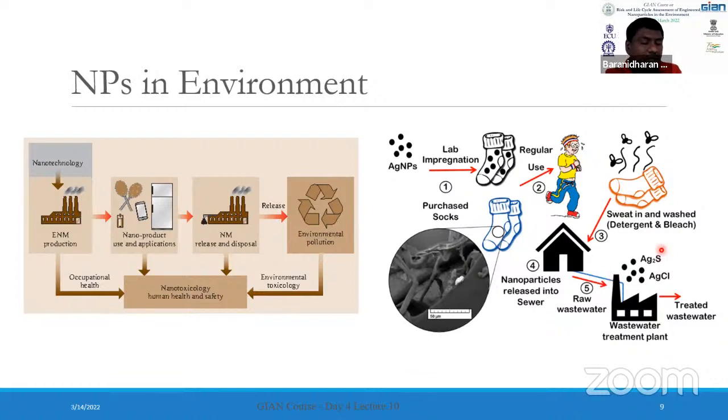Because wastewater is a heterogeneous mixture where you have the water quality parameters, the waste that gets carried out, the oil and grease, all playing a vital role, and the material that floats in the wastewater. So you have suspended, dissolved, colloidal systems in place, and all these influence the nanoparticles, which are nothing but a new entry into the wastewater. So either they can form complexes and get associated with the wastewater or get settled, or otherwise they can stay back as such. So the $1,000,000 question is whether it is there in the wastewater treatment plant or in the treated wastewater. Both are a matter of concern.